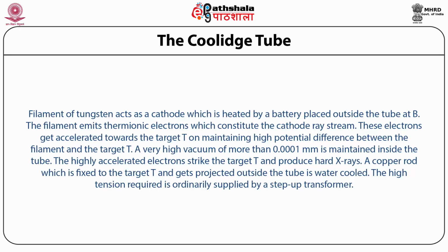A very high vacuum of more than 0.0001 mm is maintained inside the tube. The highly accelerated electrons strike the target T and produce hard X-rays. A copper tube, which is fixed to the target T and projects outside the tube, is water-cooled. The high tension required is ordinarily supplied by a step-up transformer.